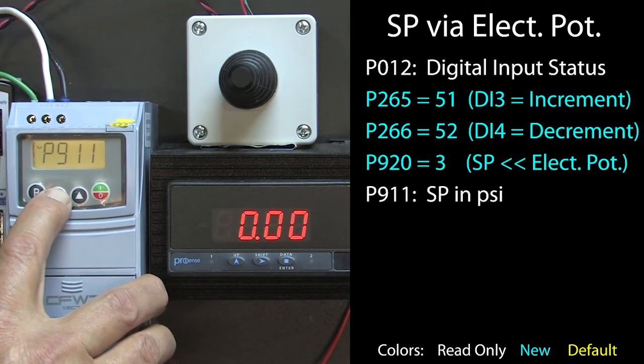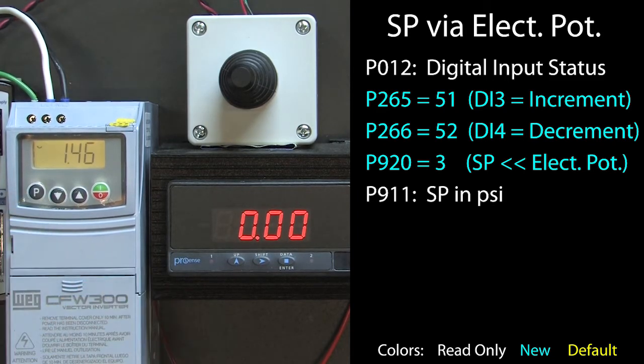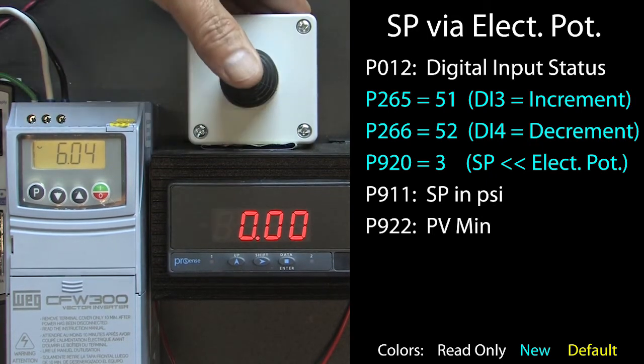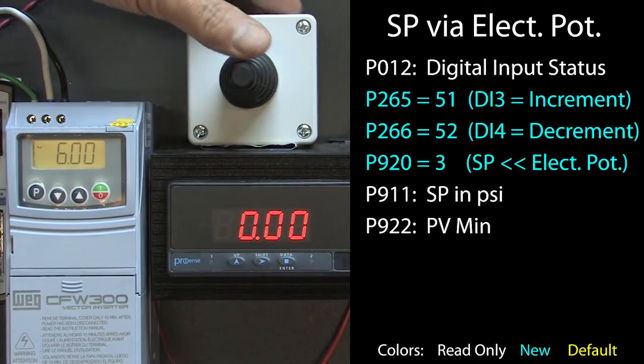If we go to parameter 911, we see that the electronic potentiometer defaults to the minimum process variable value that we put in parameter 922. I'll hold the joystick up to scroll to 6 psi. Toggling the joystick just increments or decrements the value one at a time.